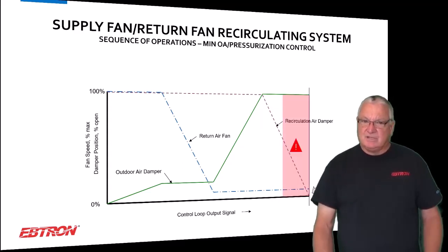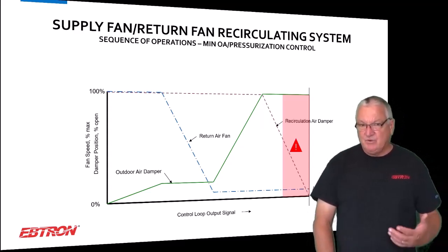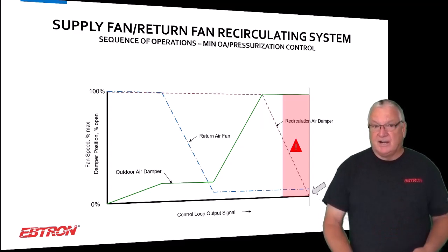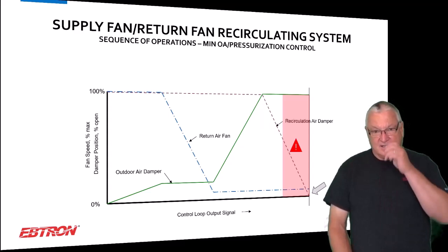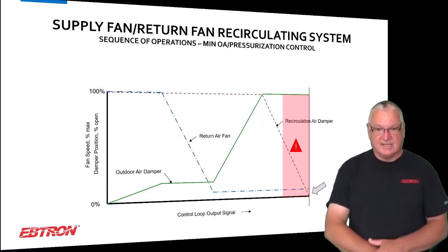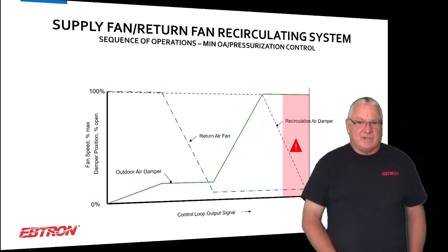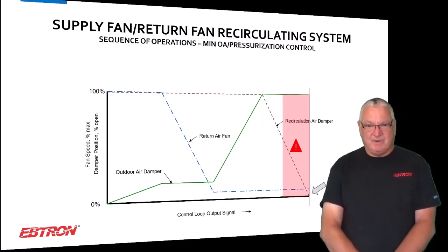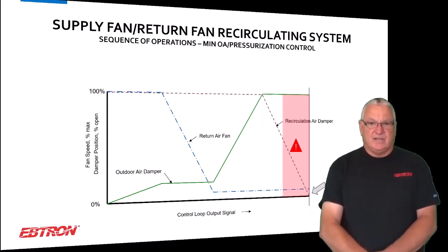And I just put this little kind of red thing in here that obviously if you close that damper, if you look at this sequence, you'd blow the air handler up, okay? So you don't want to be there, and one of the things that I don't talk about is where you should put alarms and shutoffs and things like that. I just showed a whole sequence, okay? I'm assuming that people that are implementing this understand that this would not be where you want to be. But it's the whole sequence. This works very well. We've been doing it for years.